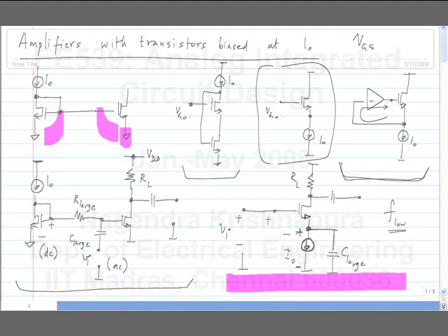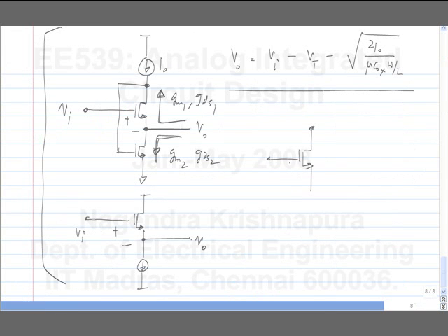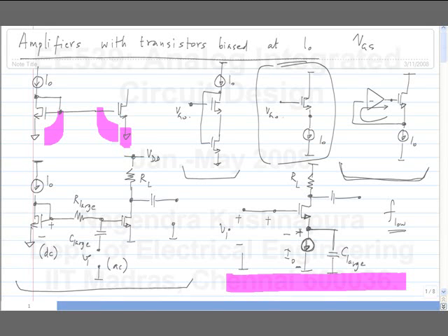When I started off deriving those, I imagined a fictitious transistor like this, where the controlling nodes are completely separate from the controlled nodes. Now this connection is already there in a real transistor. In the model of a real transistor, this terminal is already connected to this terminal. So that gives you implicit feedback. In fact, if you look at this circuit, there is no explicit feedback, right? You don't see any loop.